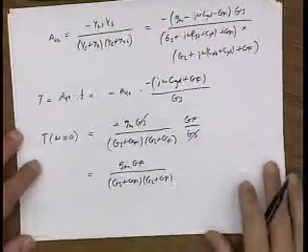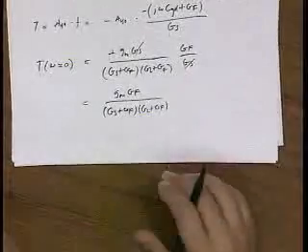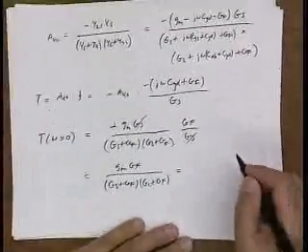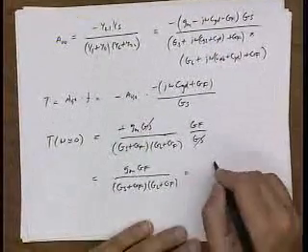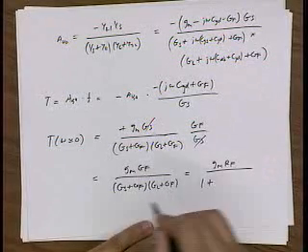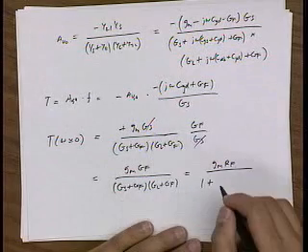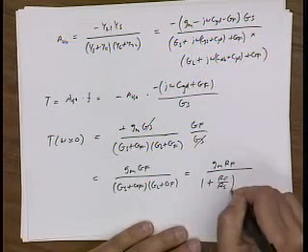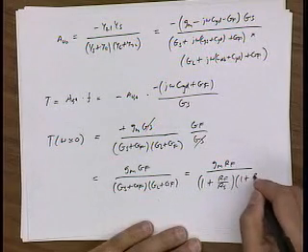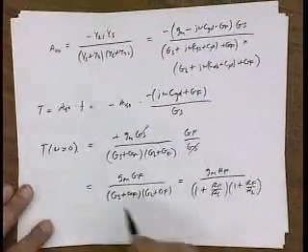And since most of us tend to think in terms of resistances rather than admittances, let's just divide this equation by GF squared. So then I get GM RF here, and here I would get 1 plus, put 1 over GF here, 1 over GF here, GS over GF, which is RF over RS. And here I would get GL over GF, which is RF over RL. Okay, so this is my loop gain.